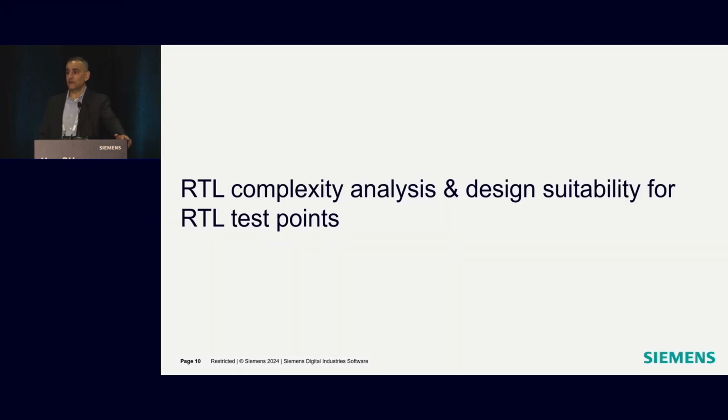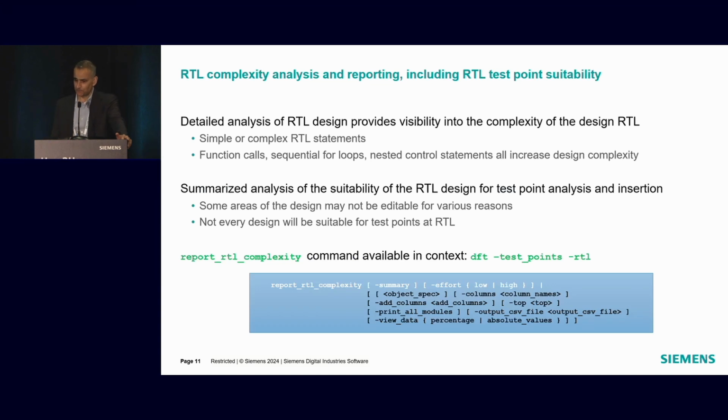So as part of that, part of the analysis the tool does, we now also do RTL complexity analysis and suitability analysis. What this functionality does is the tool will look at your design, and before you even have to go through all the other steps, it can give you a very nice detailed report so that you can see, first of all, at a high level, is my design a suitable design for RTL test points? How complex is it? And where are the complexities in the design?